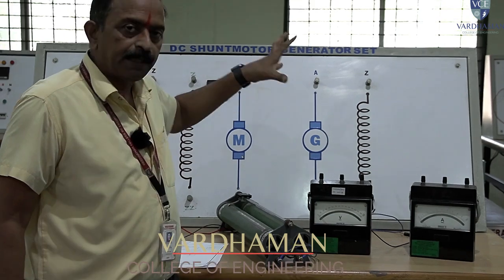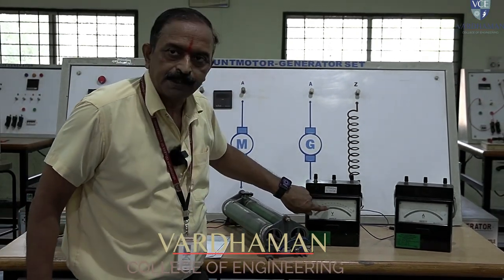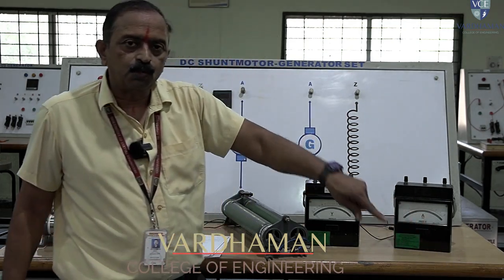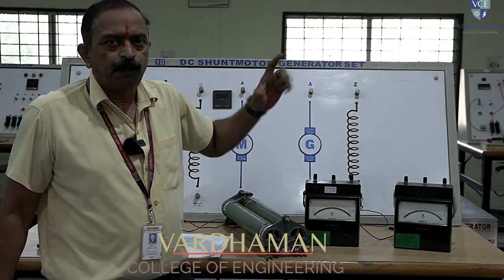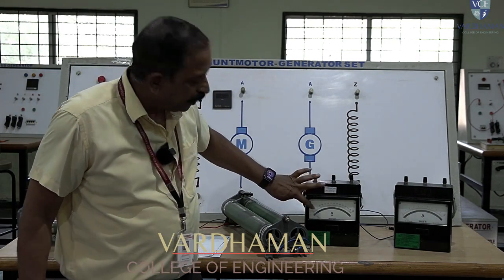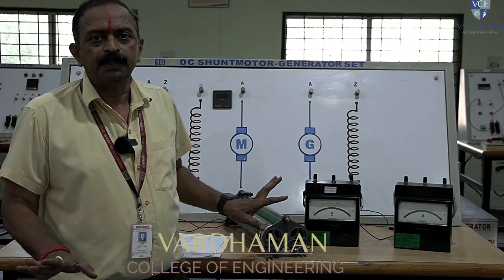As dφ/dt, the change in flux, varies, the voltage also increases. So gradually increasing different currents within the range of 0 to 0.48 for different φ values, for every step of current we will note down the voltage induced in the armature terminals. That is the experiment here.